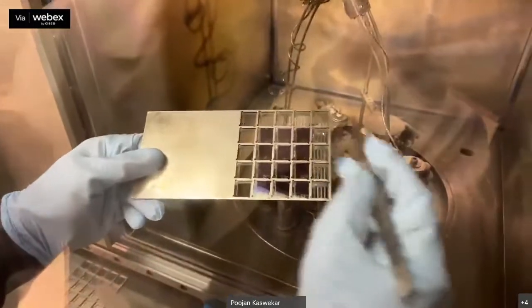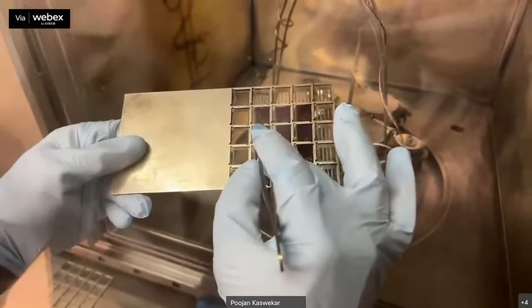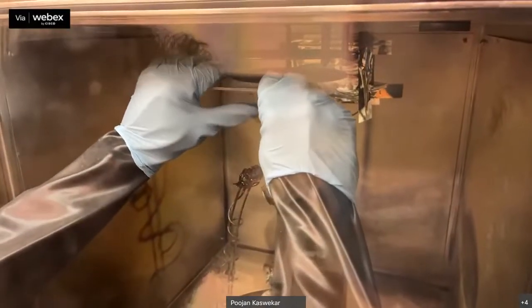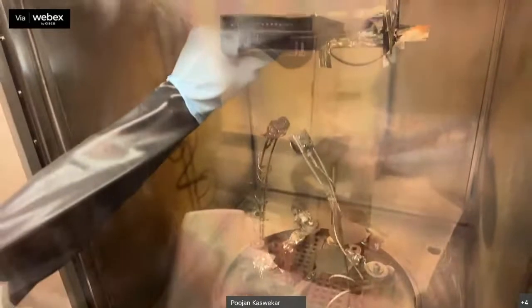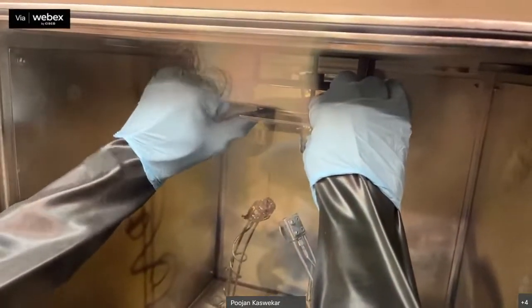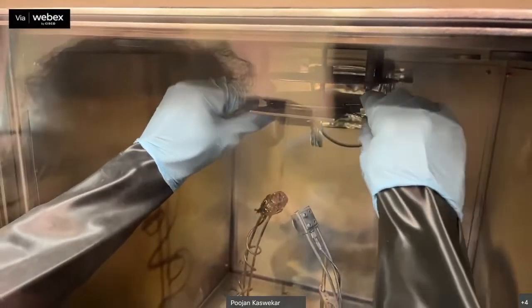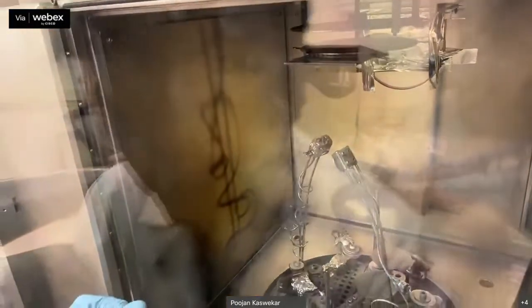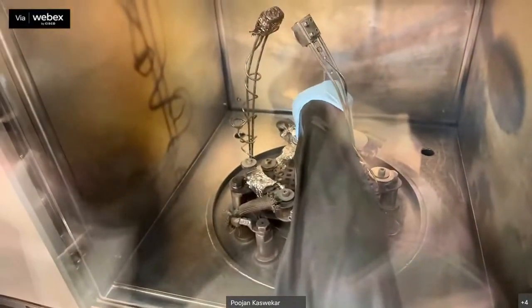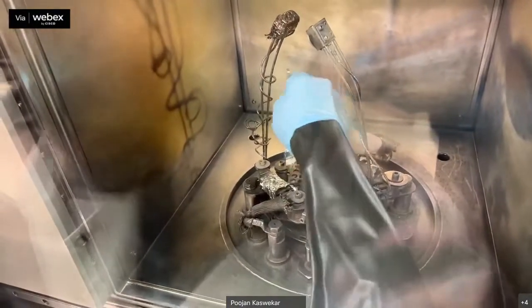So now you can see the samples, right? This is the etched area for the bottom electrode, and the 4 electrodes will be etched on top of that. This is the masking area. We'll put it here carefully without disturbing the samples, and we are going to clip them. The samples are resting on the rotary plate, which is going to rotate. And this is the silver plate, where we will put our silver pellet.